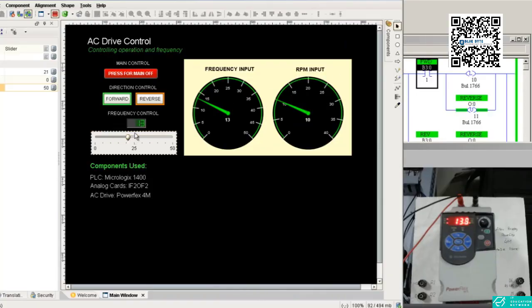When I take it beyond, it goes to 21, so it will accelerate to 21, and you can see that 21 is here, and this RPM is 17 RPM, because the motor we are using has 1350 RPM maximum, but with a gearbox having a gear ratio of 40, which is fixed. That's why RPM is 17. Now if you increase to 29 Hz, that leads to 23 RPM.